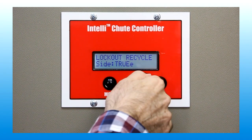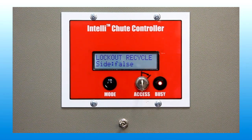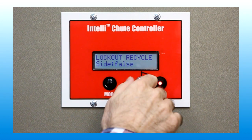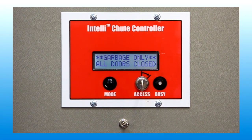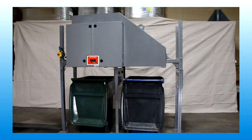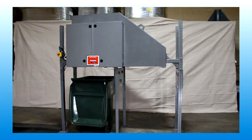The Lockout Recycle Side parameter provides a lockout function on the recycle side of the BiSorter in a similar manner as the Lockout Garbage Side. To enable, select True. Set the toggle switch back to the enable position, and in this case, the BiSorter operates as if the recycle side does not exist.